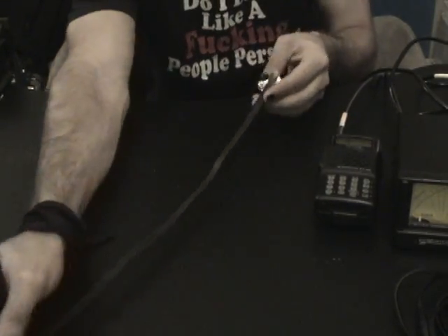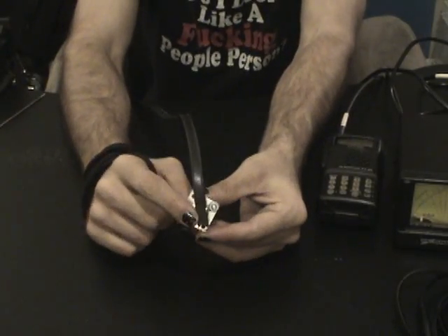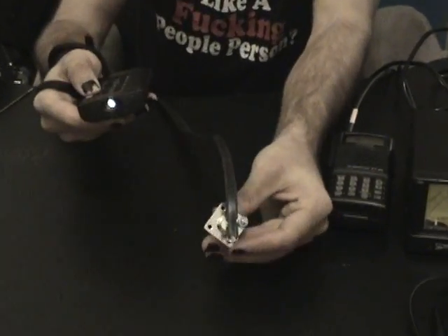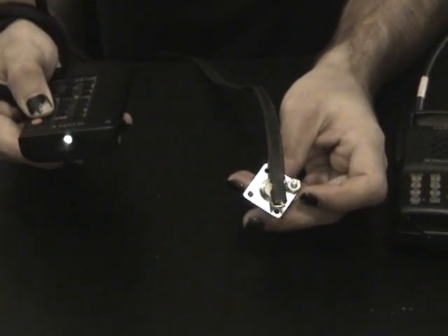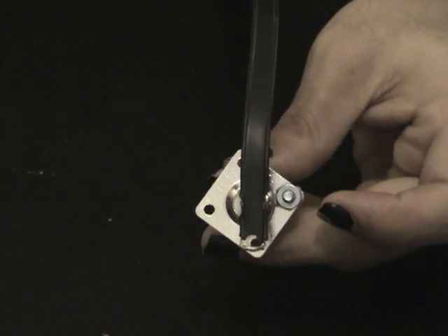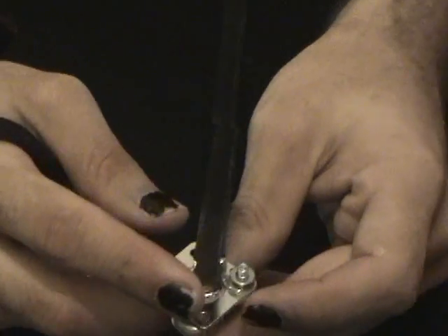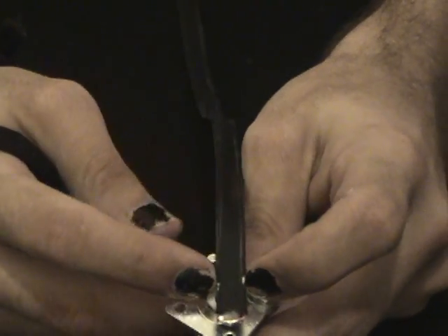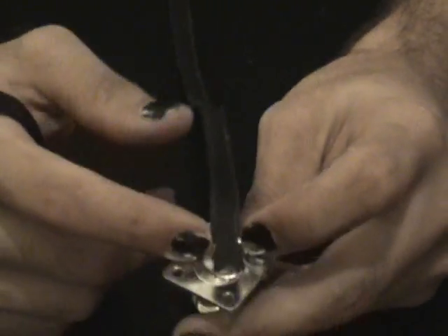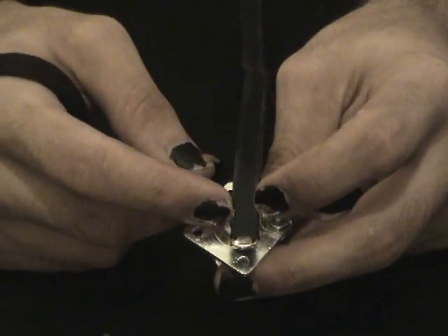It's literally just twin lead. What you need to do, per instructions, is first, let me zoom in a little bit so you guys can see this. Okay, now, according to the instructions, the first thing you need to do is actually solder and bridge the bottom over here. Now, a 1/4 inch on the instructions, it says anything on the 440 megahertz band. You need to make a notch and strip away to the bare copper so we can have our feed point.